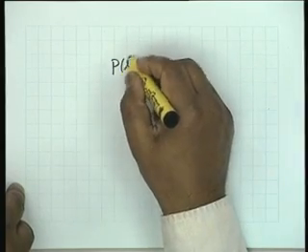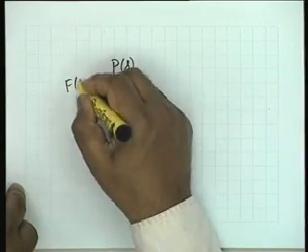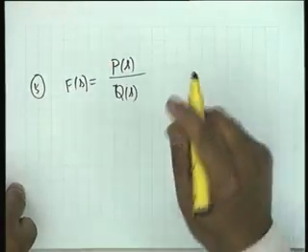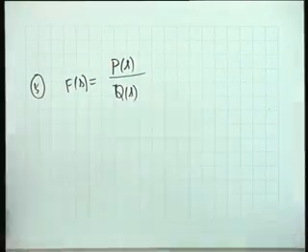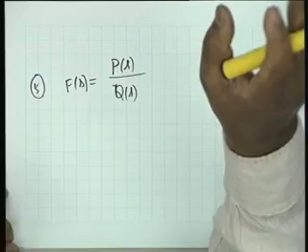Next, fifth property. Suppose f of s, now we bring in a further restriction that the positive real functions that we shall deal with are all rational. If you have a finite number of resistors, capacitors and inductors, obviously the impedance function or admittance function, any network function, has to be rational.